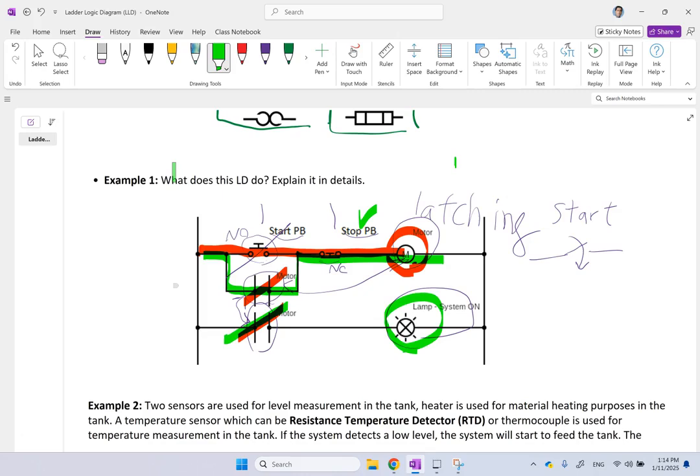You turn a motor on with an on button by pressing it one time, and a light will show. As long as the motor is on, the light will show that it is on. When you press the stop button, both the motor and light will go off. Pressing the on button one more time is not going to affect anything. So that is very, very simple ladder logic.